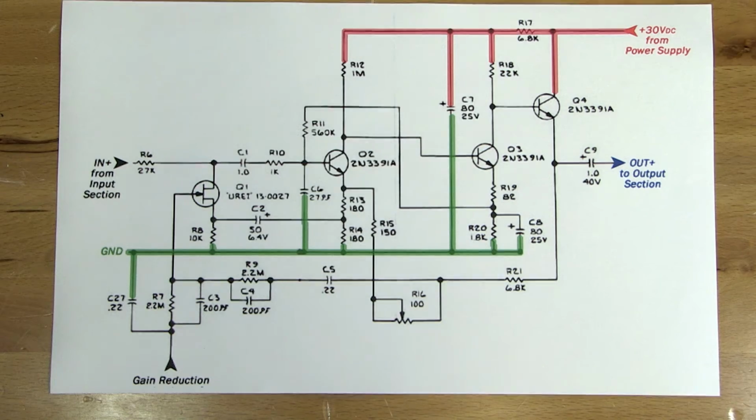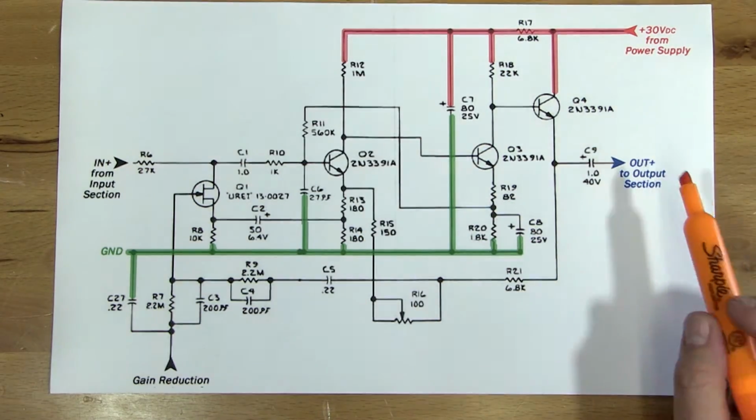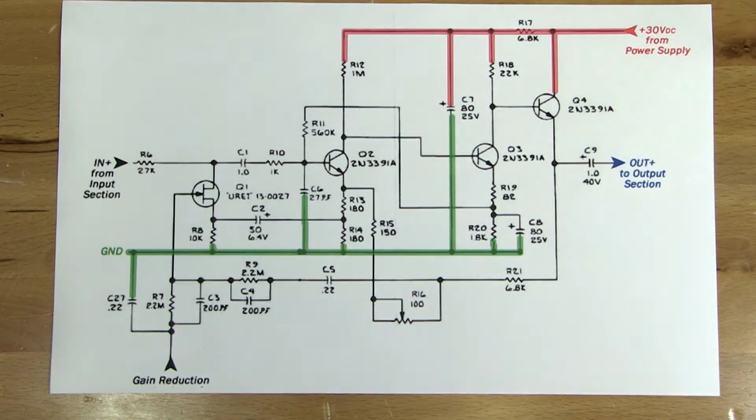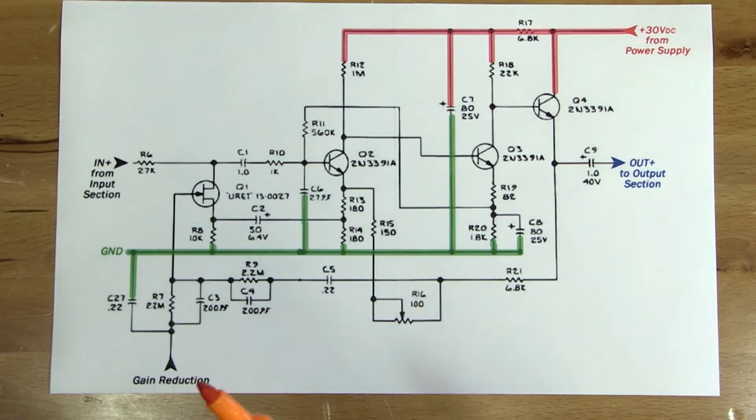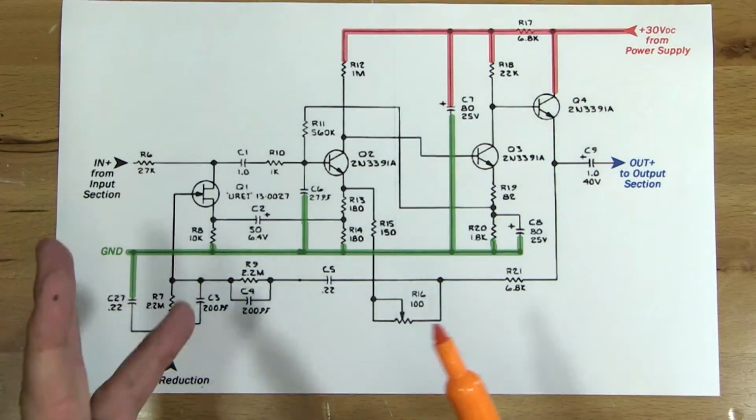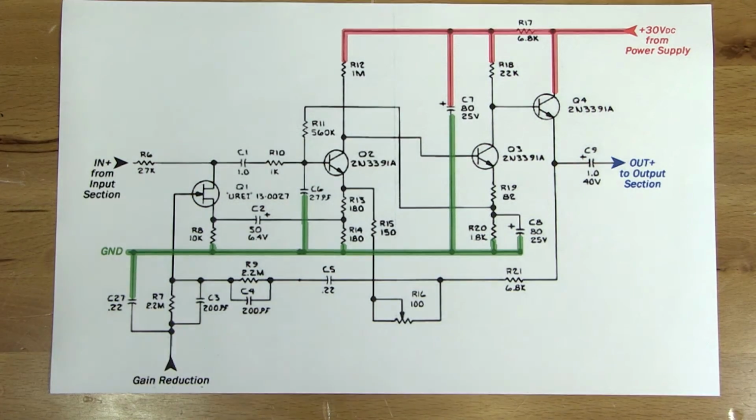It's useful when you do this to ideally do each active component in a different color. You could also do it on separate pages, but a different color is really useful. So if you need to go spend a couple bucks on a bunch of colored highlighters, it's definitely worthwhile. Again, the whole idea is to make the schematic visually more useful to you. So put lots of information on it. And each of these steps that we're doing should be simple on its own, but provide you a lot of information.